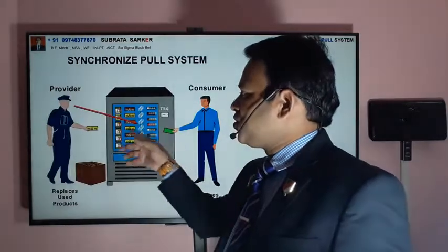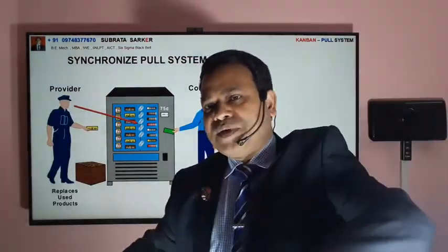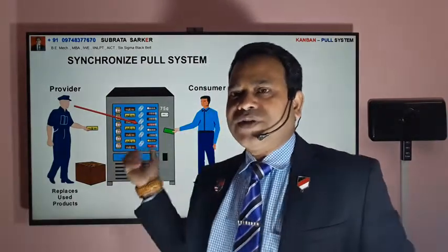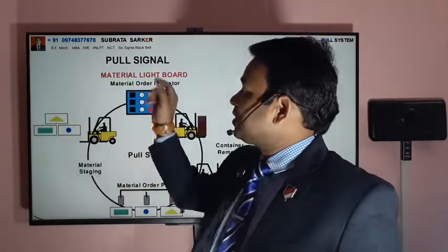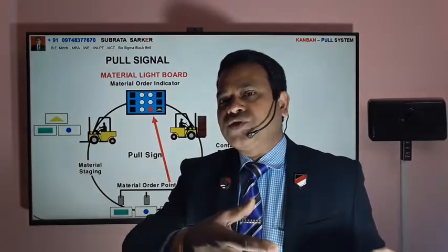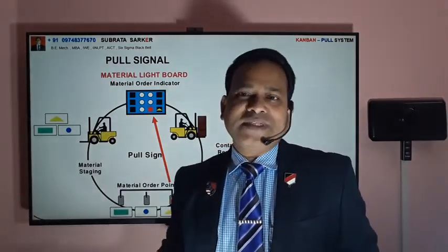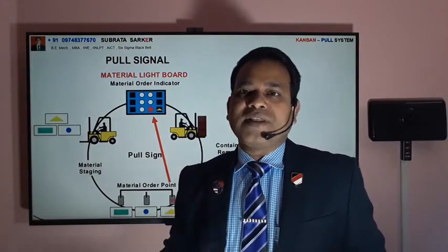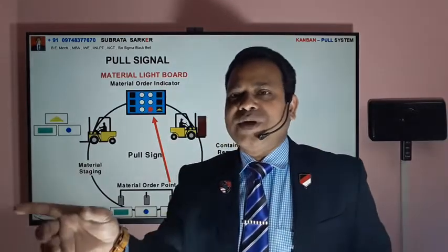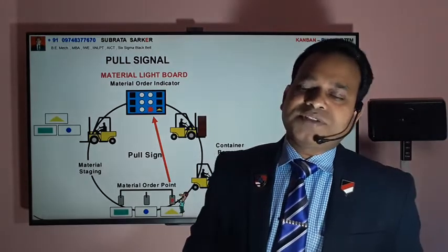You can see here in this picture, like one part you consume in production, immediately another part comes from the store or some other place. So there is always a pulling system, actually, you can say here. And there is a pull signal system in Kanban, as I already said. So you take some parts from the store, give them to the workstation, they do the assembly of the parts, they immediately give a signal, a communication to the store that 5 parts are consumed, and the store again gives 5 parts and puts them into the particular station. So this is how the signaling system actually works.